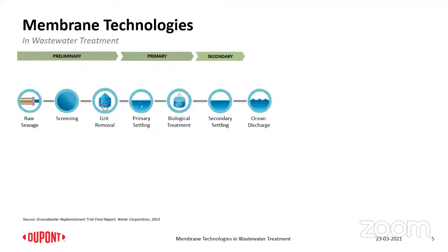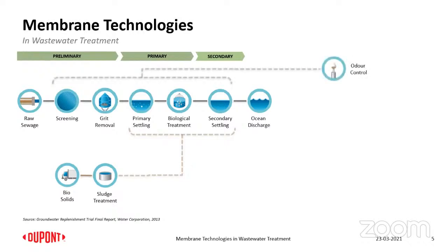It is sometimes discharged into the rivers based on the municipal discharge norms, or disposed into other water bodies nearby, or pushed into the ground. The sludge is usually subjected to sludge treatment. So this is anyway there, this has to be there. And the sludge biosolids are taken for either agricultural purposes or drying places where it is either reused or safely disposed. The odor that is generated is controlled, and the odor control or the atmospheric pollution is also checked there.